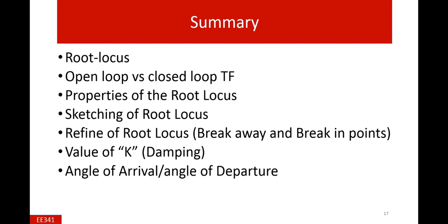And similarly, the root locus starts from k equals 0 and at k infinite ends at the open loop zeros. If that is not happening, if the number of poles is larger, which is our general case, then what are the guidelines to draw the root locus? Then we take the asymptotes and find the center of asymptotes, and then the angle of the asymptotes.